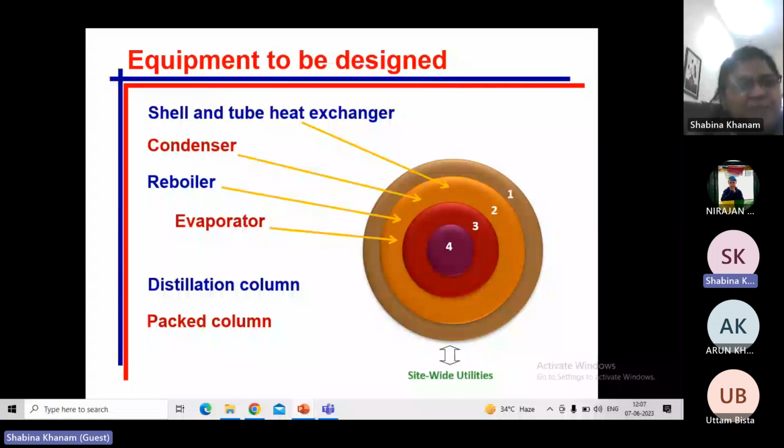So this evaporator takes the solvent from the slurry to make a more concentrated slurry. That is done through heating. When we consider this evaporator in detail, you can see that the heat exchanger is an integral part of this evaporator. So it is a heat exchanger layer as well as a separator layer, because it has to separate the solvent from the slurry. How it is separated, all that we will cover in the evaporator, so you can contribute in both layers, separator as well as heat exchanger.